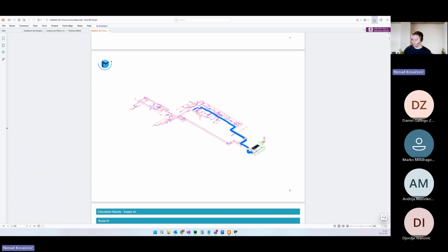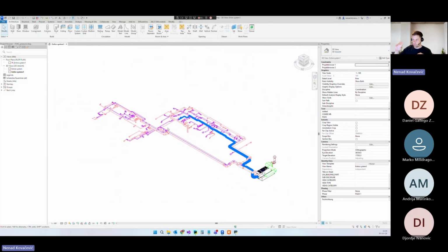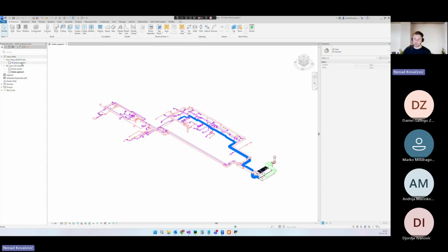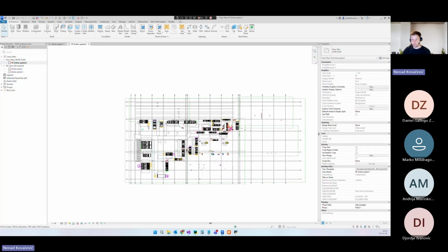Also, we are saying that if you are in the 3D view, we will do some post-process. We will zoom out, create a snapshot, and place it in the report and exit. But you can also be in any view if you want to create this image from the floor plan. You can also be in the floor plan over here.